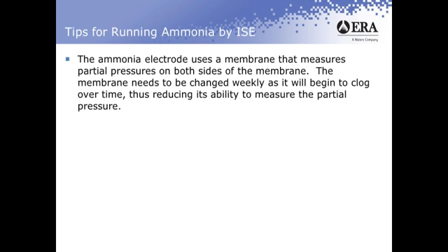Well, over time, that membrane will clog. The filling solution, the sodium hydroxide and the methylene blue in those solutions will tend to clog the pores of that membrane. So I would recommend that you change that membrane at least weekly, so that you can minimize the amount of clogging, because as it clogs, it reduces the ability to measure that partial pressure. So you want to reduce that issue by changing that at least weekly.